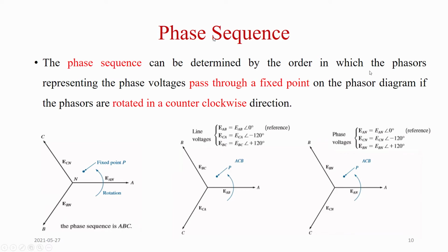This is just to explain the sequence. Basically, the phasors rotate this way. So if you're here, what is coming after? B. Then what is coming after that? C. Now this is anti-clockwise, the rotation of the sequence. And it makes sense. This is the phase: this is angle 0, then goes to 90, goes to 180, goes to 270, goes to 360, which is 0.